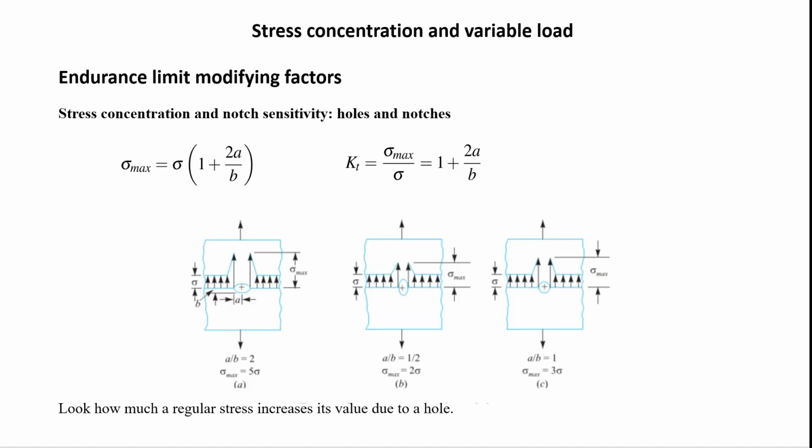Well, depending on the type of imperfection you are dealing with, you are going to have a certain level of stress concentration. And this is an example. This is a plate, and the plate is subjected to axial tension, this one and this one. Imagine that there is a force applied here, and the same force here. For sure, the stresses are going to be represented like this, but in the middle, there is a kind of hole, an ellipse oriented in this way.